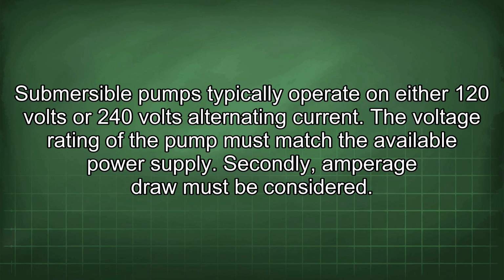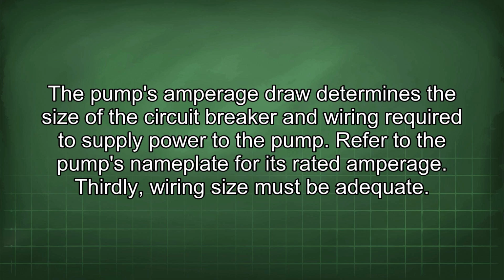Secondly, amperage draw must be considered. The pump's amperage draw determines the size of the circuit breaker and wiring required to supply power to the pump. Refer to the pump's nameplate for its rated amperage.